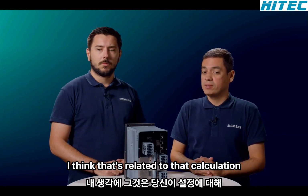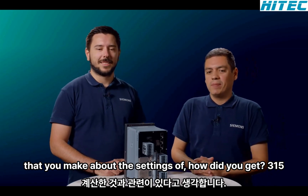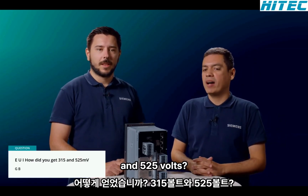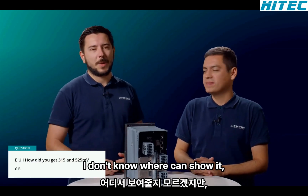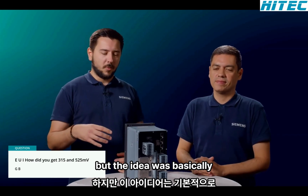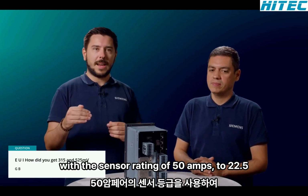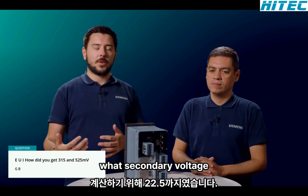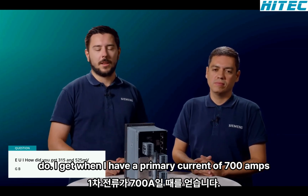And one question, I think that's related to that calculation that you made about the settings. How did you get 315 and 525 millivolts? Unfortunately, I don't have a whiteboard now where I can show it, but the idea was basically with the sensor rating of 50 amps to 22.5 millivolts, to calculate with this ratio what secondary voltage I get when I have a primary current of 700 amps.